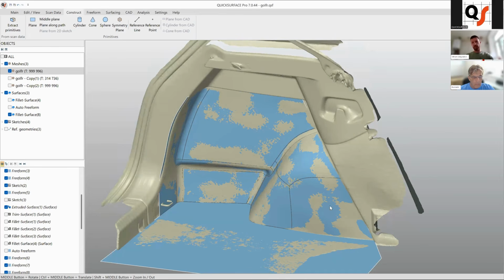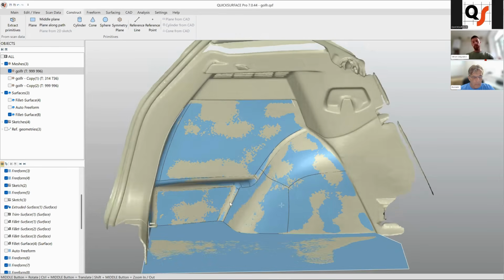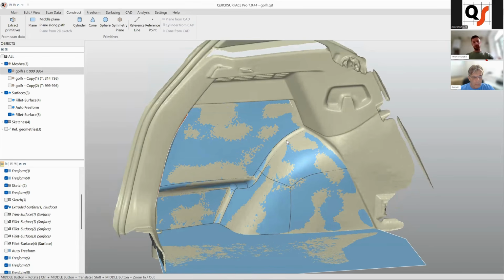And pretty often I have seen results when people come over from this stage, you have here like 20 quads, and you move all of them to the one corner. So here you have, for example, let's say it's one meter length of the edge, and here you have 20 centimeters. So you can imagine this moment when all these 20 points come to spacing of 1 centimeter instead of 5 centimeters.